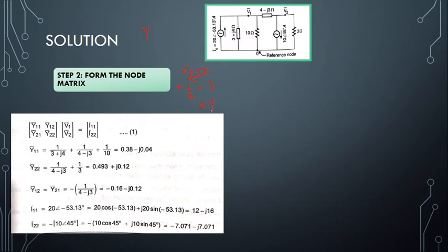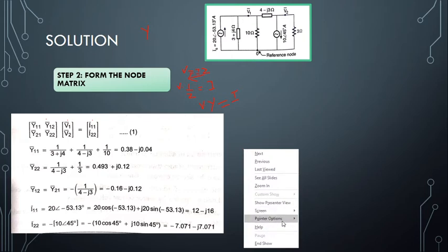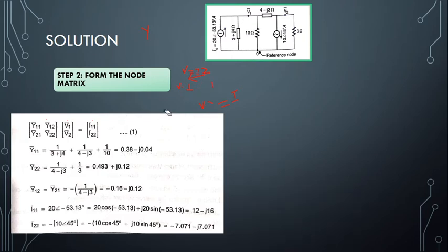So it becomes V times Y is equal to I, where Y is what we define to be the admittance term, which is nothing but the inverse of impedance. That is how we got this matrix. V times Y is equal to the I value. So this is also obtained from Ohm's law and nothing else.